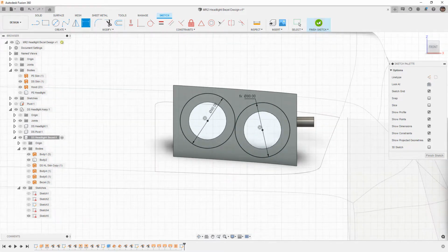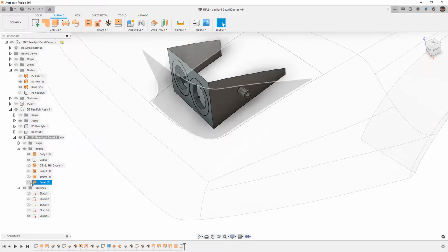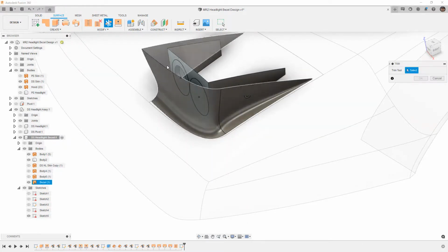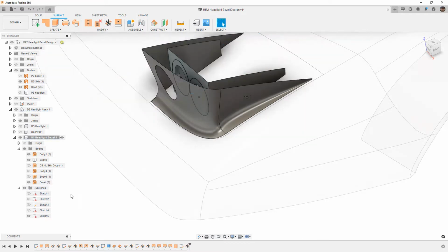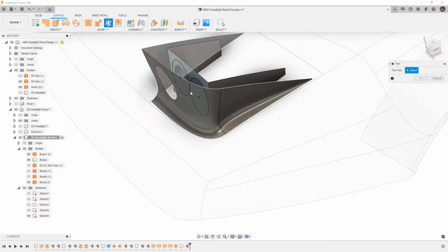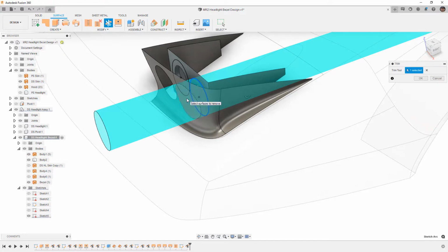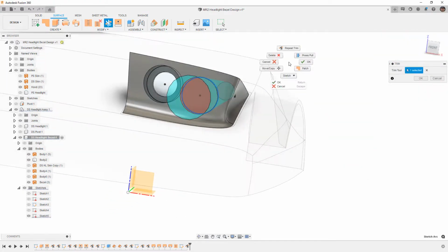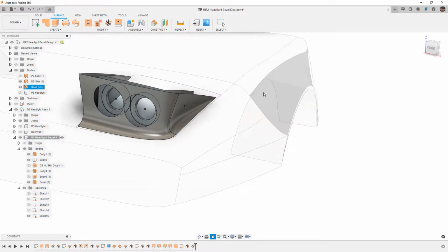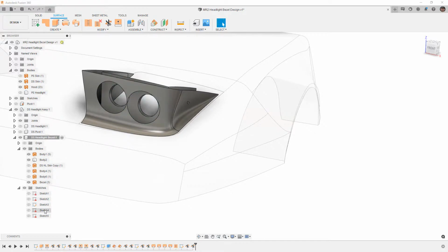All right, so now that I have this, bring back my bezel, and now I want to trim it. So trim tool, get rid of that, say okay, right click, and I'm going to repeat the trim tool, get rid of that. And again, we might need to rotate it to make sure. Also note that the right click marking menu has okay and cancel on it. So again, once you get comfortable with that right click menu, it can be pretty fast.